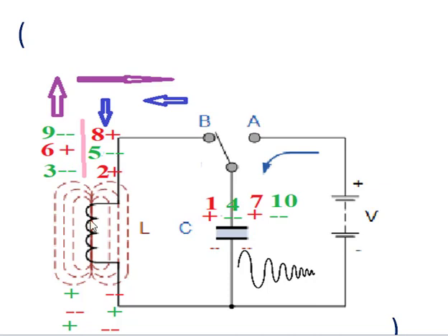During the shrinkage of the magnetic field, again it produces the induced EMF with the opposite polarity. So from negative to positive. Again this positive voltage charges the capacitor. Again it gets to maximum. Again it starts to discharge. So this process repeats.